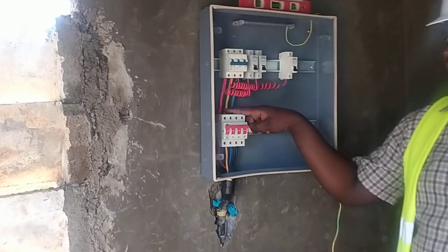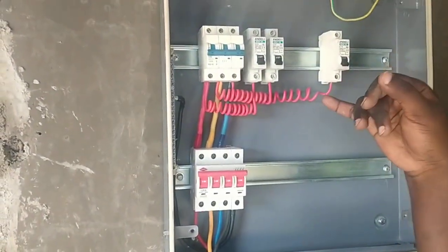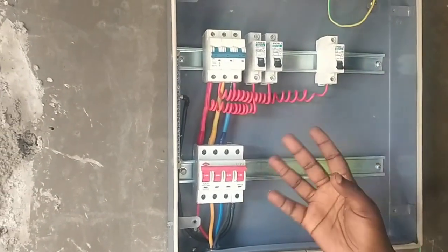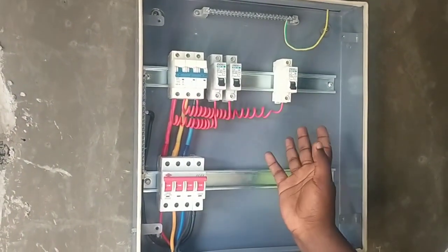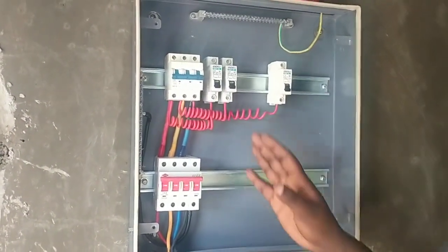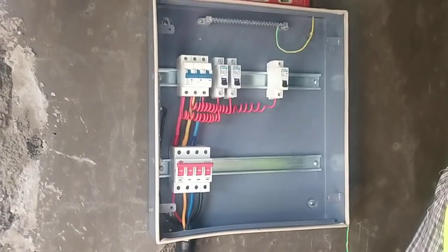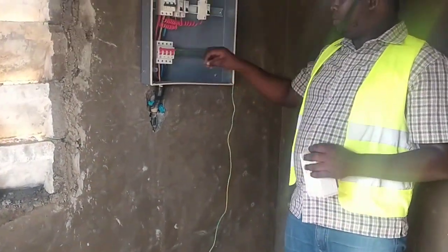As you can see from our circuit, we are doing RYB, which is very important. It alerts any electrician coming into this board about the termination. In case you are doing phase sequencing or want to troubleshoot a particular phase, it is quite easy to show that.